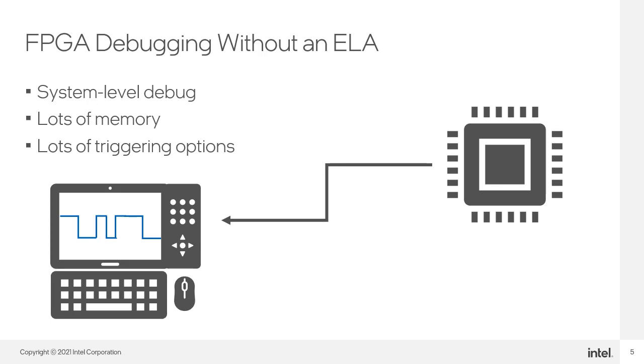However, there are a number of disadvantages. Any signals you want to monitor must be physically accessible on the board to allow for attaching a probe to the signal. This requires extra planning for the board design, including the addition of built-in test pads, headers, or connectors to allow for connections to all the signals you expect to monitor after the board is built. If you later realize that there are additional signals you need to monitor, a new board must be built.